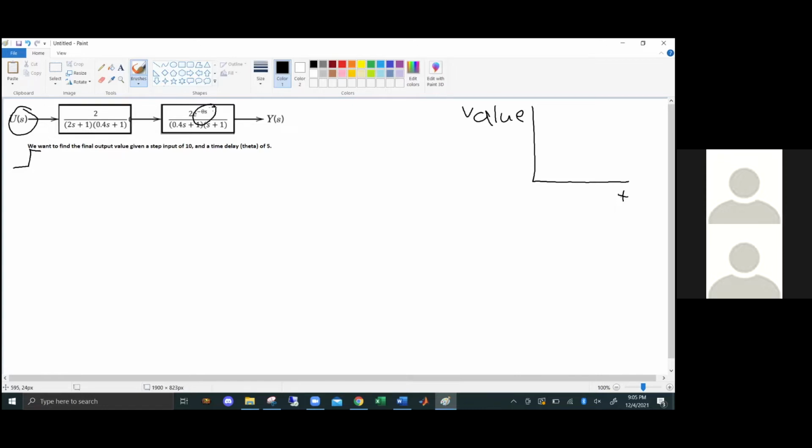The transfer functions, for those who are unaware, represent how the system responds to different inputs. The transfer functions are these two equations in the boxes here. Each component in a system will have a distinct transfer function to model its response, and this will usually be given to you in any setting. In this example, there are two components influencing process response. When solving manually, we start by multiplying each transfer function together, as they are multiplicative when in series. This lets us use an overall single transfer function to model the entire system for convenience.